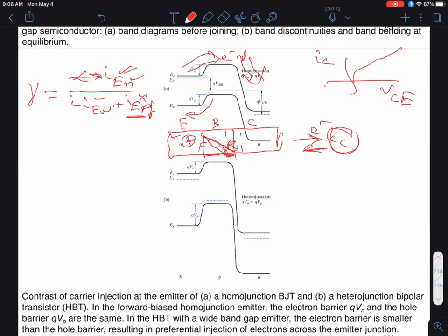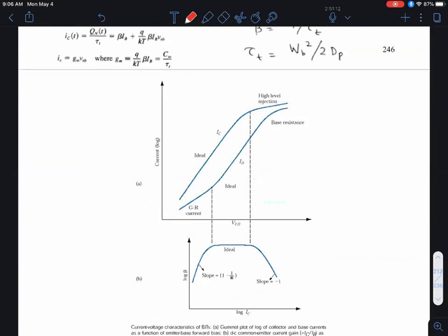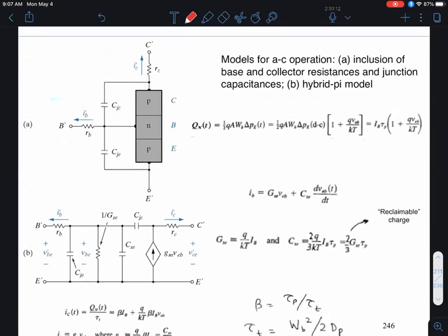All right. The other reason why you can't keep reducing the base doping is clearly if I reduce the base doping, my base series resistance is going to keep increasing, right? And that's not good because if you remember what we discussed at the end of the last class, and you look at the equivalent circuit, we saw that the base has an effective parasitic resistance RB, which is shown in a simplified model over here, and a more elaborate model down below. This is a so-called hybrid pi model, because the circuit kind of looks like the Greek symbol pi with a lot of imagination. Okay, so that's my RB in a more elaborate model, and this is sort of the bare bones model.